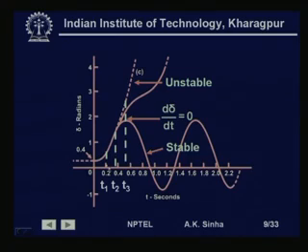This we can also, as we had seen earlier, see with the clearing time aspects. Now, here we can see something very peculiar which happens. If we see these three responses, this response is for a stable system, and these two responses are for an unstable system. Now, when we see this response for a stable system, what we find is that the delta angle keeps increasing, and after some time it starts falling down.